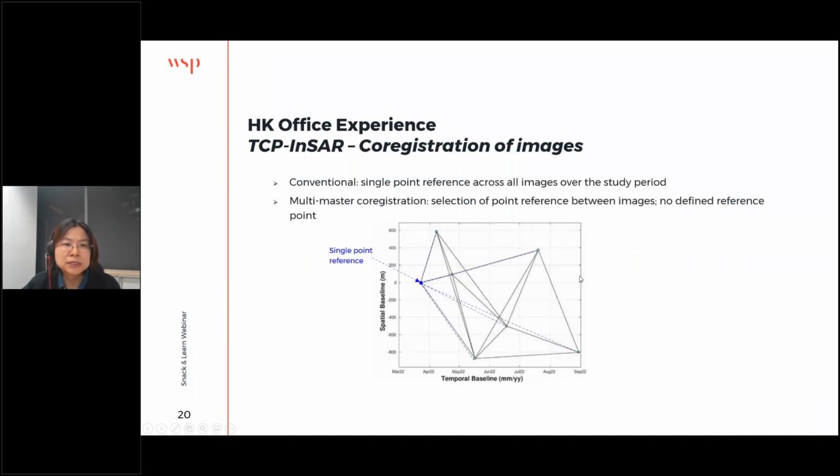Just now I mentioned that conventional InSAR uses a single master, but here, because we're using multi-master correlations, for whatever images we pair out, say 6 or 7 image pairs, we manage to find masters at certain periods. So although we have, let's say, 12 images, the master coherent at the 6th or the 7th could be developed as another master. So we no longer need to always refer to the original base case from day one. This allows us to capture what happened in between the developments.